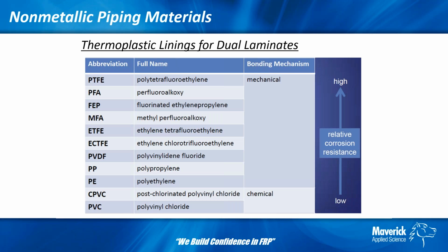So you want them all to be activated 100%, so that you get the best chemical resistance from the product that you're manufacturing. That's kind of the idea. But it needs to be defined and required in the specs from the start. Under standard practices you might not require a post-cure, but if we don't achieve the Barcol we set for this resin application, say it needs to be a 35 and we're only getting 30, well, obviously something's not coming along the way it should, and we need to post-cure to drive that cure through that product.